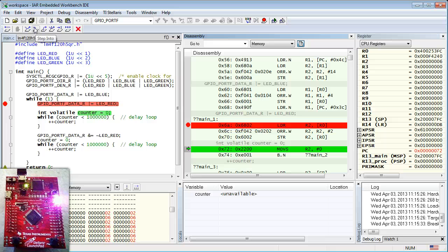But before I explain how to do this, I think it is interesting to understand why bother. After all, the read, modify, write sequence is fast enough for most cases. Well, it turns out that it is not so much about the speed in this case, but rather to give you the ability to manipulate the individual GPIO bits truly independently from any part of your code, including from interrupts.